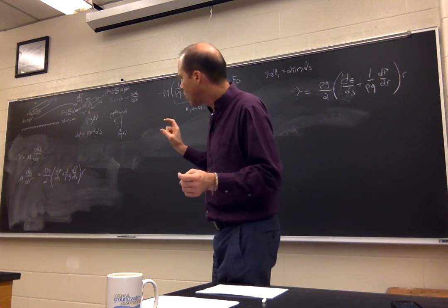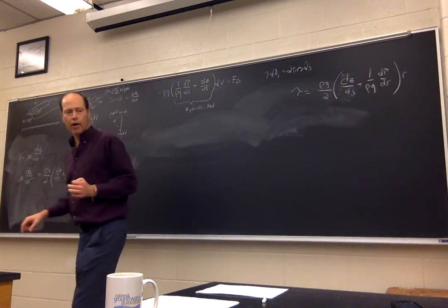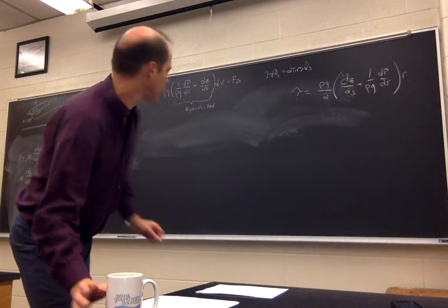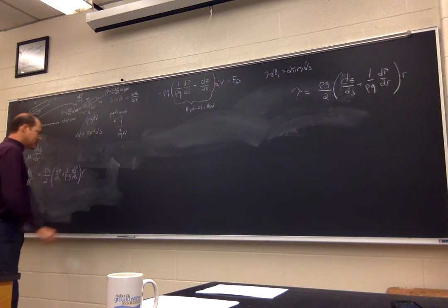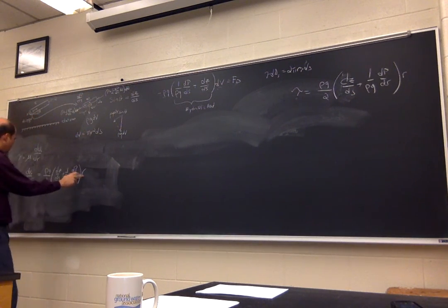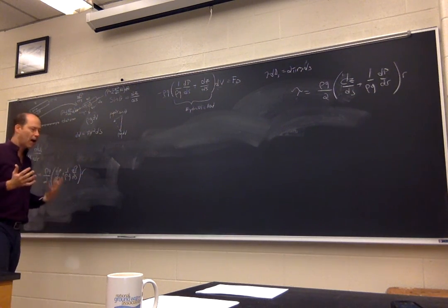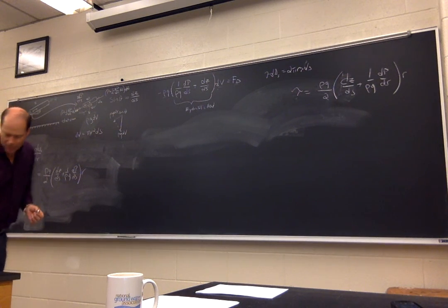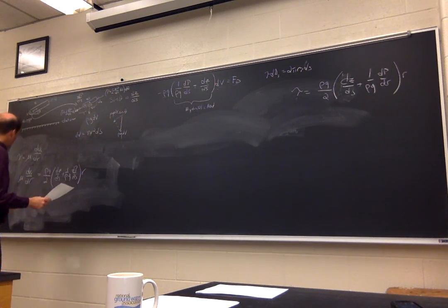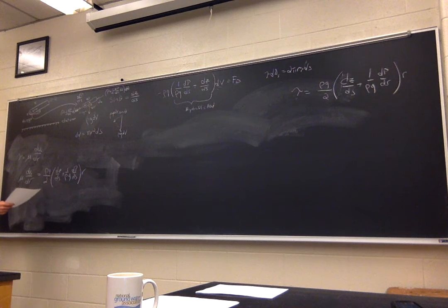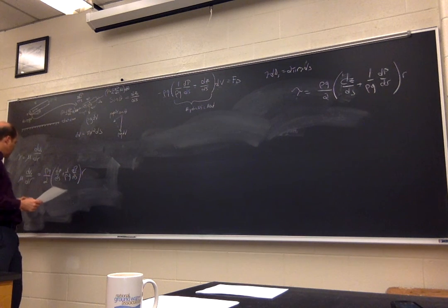So I can separate my variables now, which is the next step. I have r on this side and r on this side, so I want to combine the r's all on one side. I'll take the mu over to the other side, so that what I have is the change in velocity in the s direction on one side.